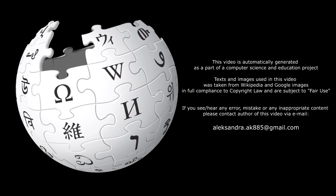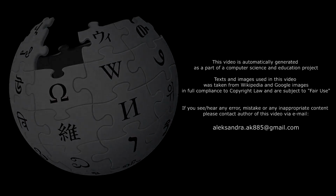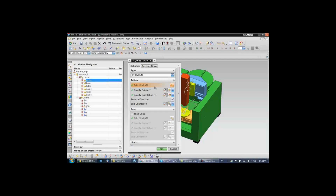STEP NC is a machine tool control language that extends the ISO 10303 STEP standards with the machining model in ISO 14649, adding geometric dimension and tolerance data for inspection, and the STEP PDM model for integration into the wider enterprise. The combined result has been standardized as ISO 10303-238, also known as AP238.